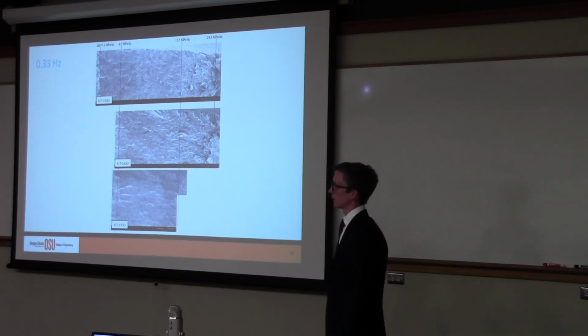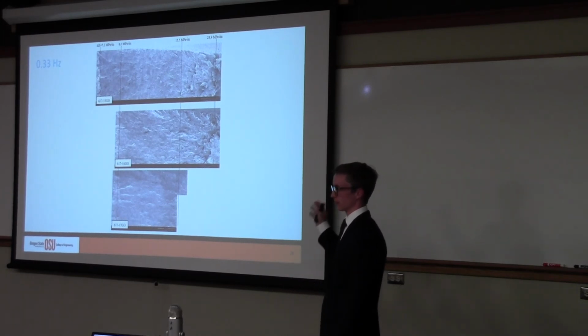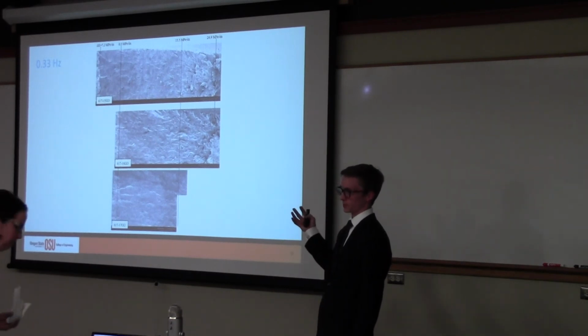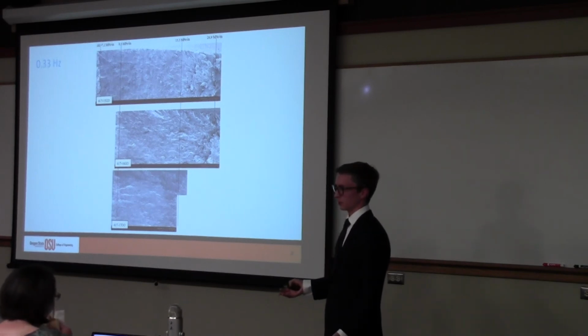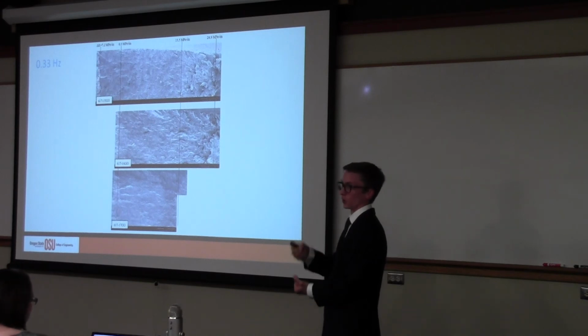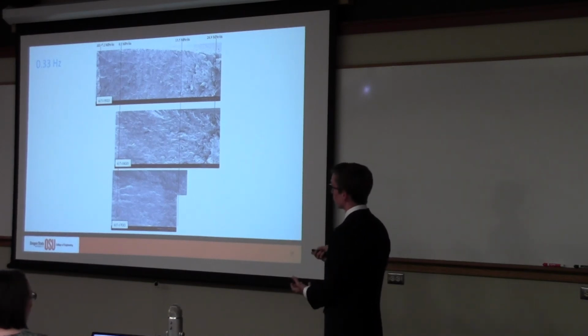Great question. The crack length is all from electric potential drop. Every one of our samples has an Excel spreadsheet with a bunch of voltage measurements that then turn into crack length. Then we translate that crack length given the load we know we're applying. It's the same load, a constant amplitude test.